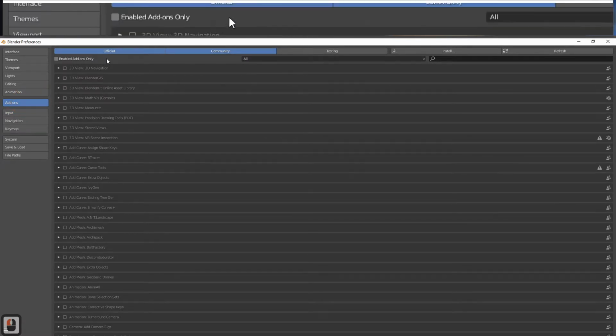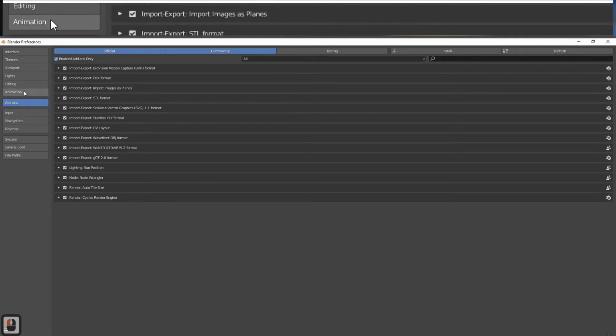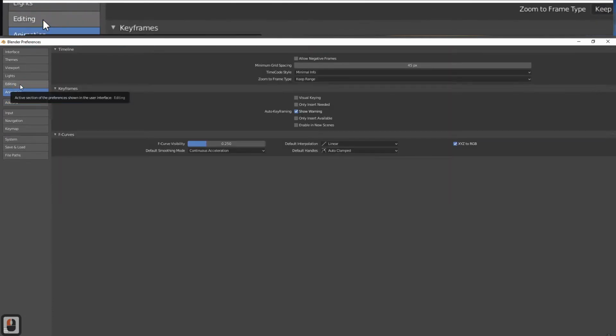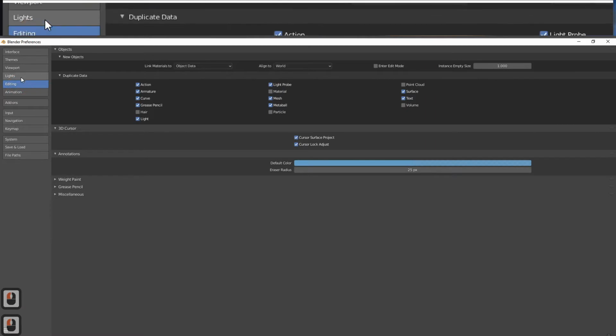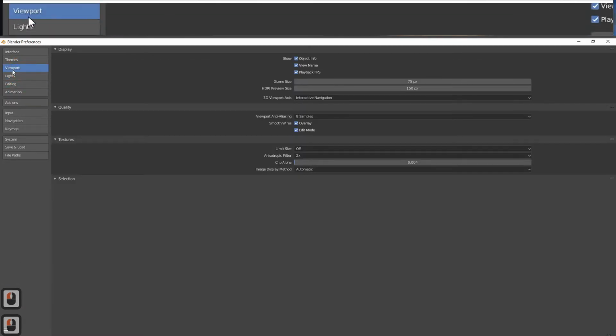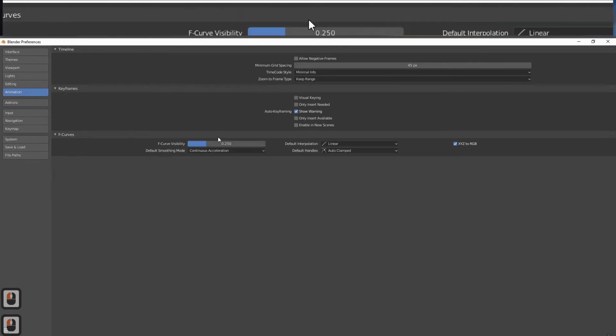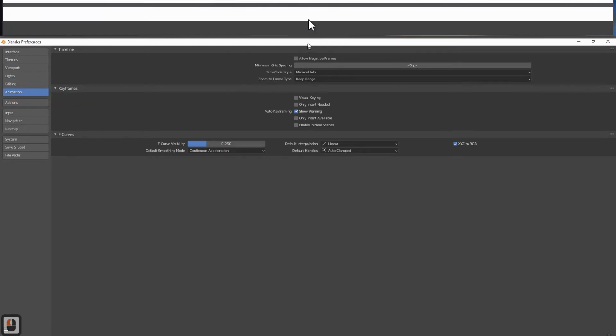At a frame, I would mark the current rotation value, and after 90 frames, I would rotate it by a positive or negative 360, depending on which way I want it to rotate. And the software would figure out all the steps in between, which simply means, in this case, it should be rotated 4 degrees each frame.